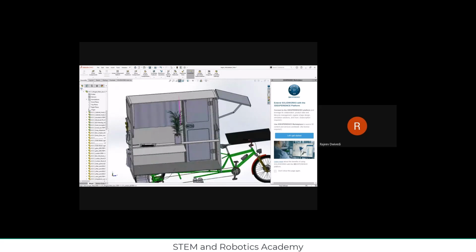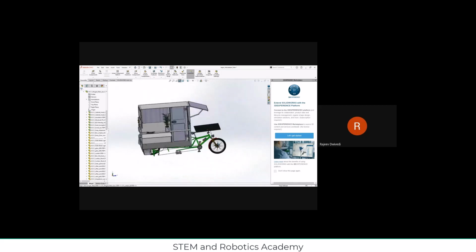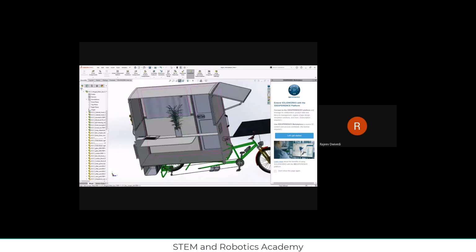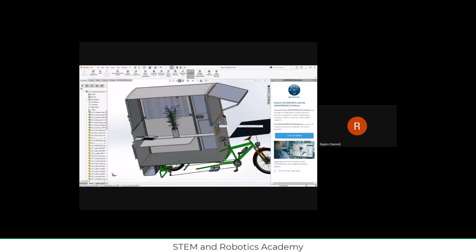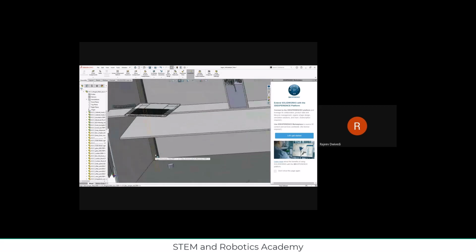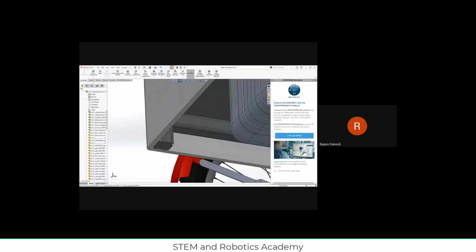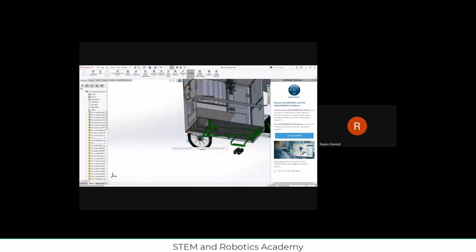So obviously, it being human powered, we can't make it super fancy, because every facility that you add to the system will make it heavier and heavier, and maybe costly too. So probably the material the person used is a very thin plastic sheet or something like that. One thing you should see is that to give strength to the structure, all around, in these corners, they have used good steel or aluminum tubing.